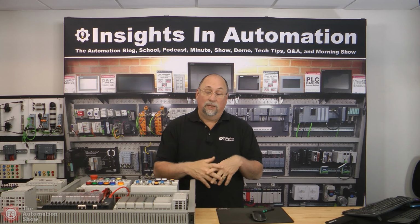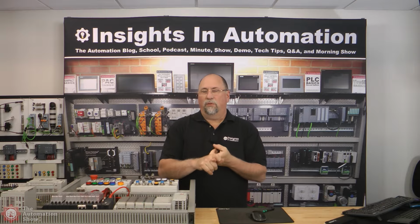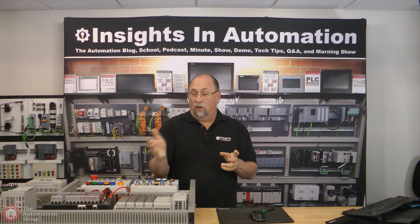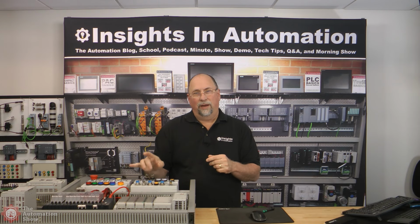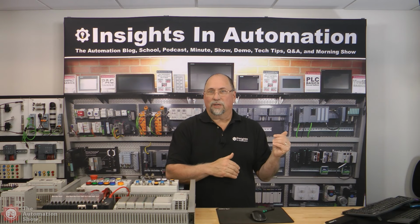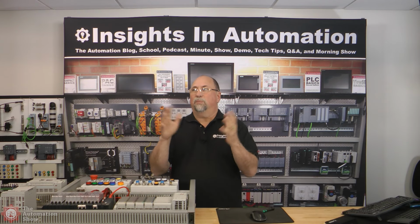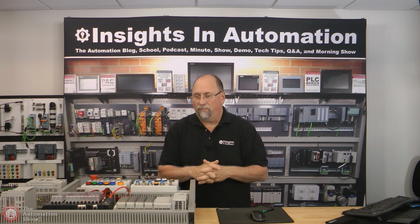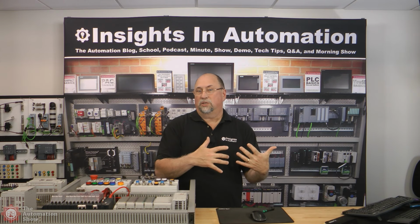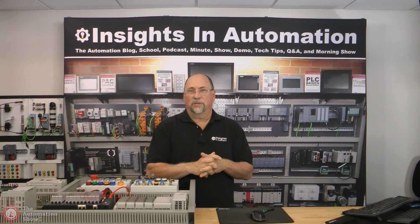address on the network. And there's a few different ways that you can do that. It defaults, you can use the default 1010 address. I don't want to change my computer, so I'm not going to go that route. Also, you can use the USB-C. The address the USB-C is at conflicts with the addresses on my network, so I'm going to avoid that as well. Probably wouldn't conflict with yours, but because I have so many devices in here, I use a Class B. And another option would be to assign it an address based on a DHCP server, but I don't think a lot of you out there are going to have that on every plant floor you visit.